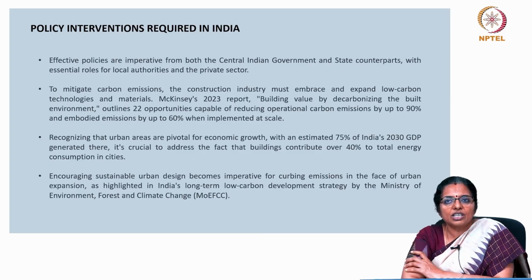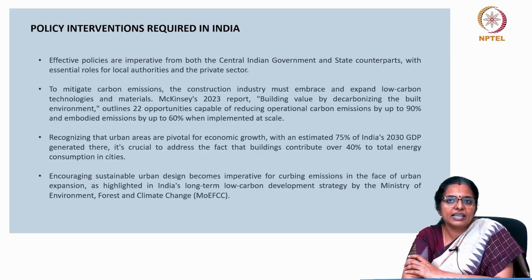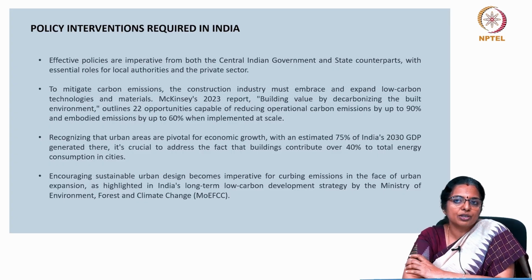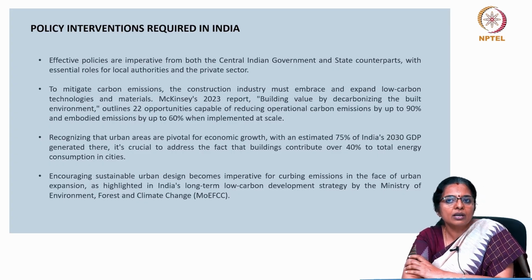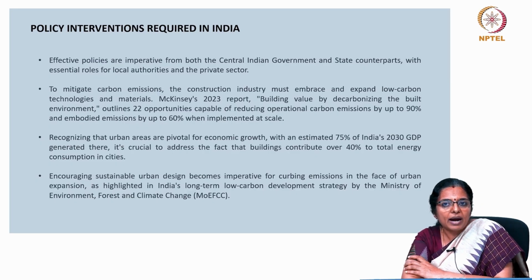The national bodies such as the Bureau of Indian Standards should enhance existing building codes like the NBC, National Building Code, to address operational carbon from the outset of new building design. It must introduce metrics that measure building performance through carbon emission alongside traditional energy consumption metrics. State governments should develop comprehensive guidelines for retrofitting existing buildings while emphasizing passive measures. The operational carbon management must also be mandated and regulated.